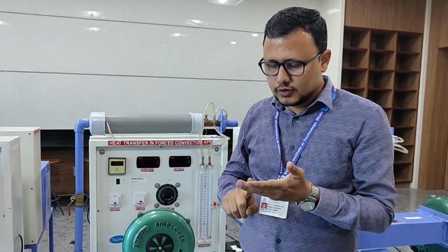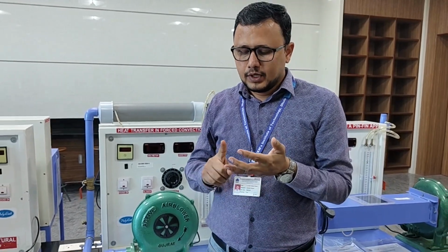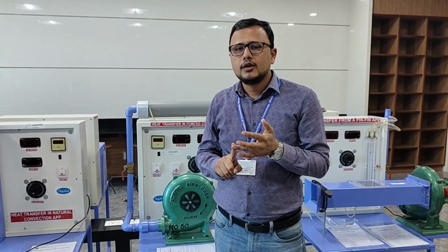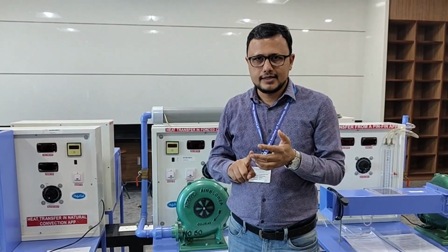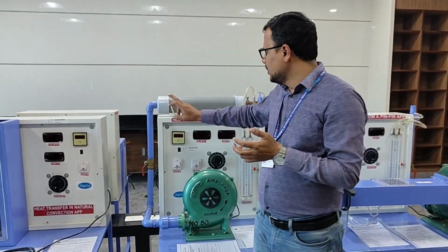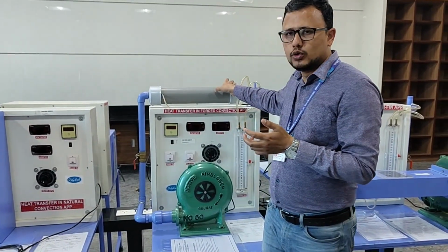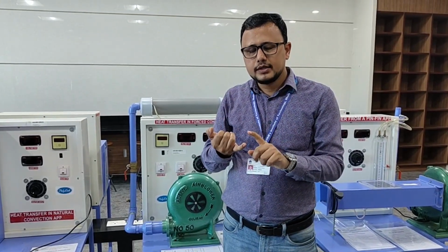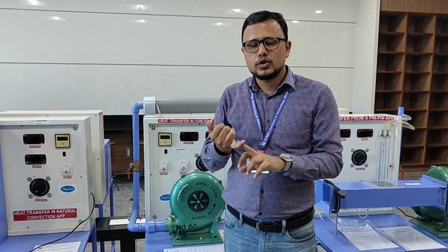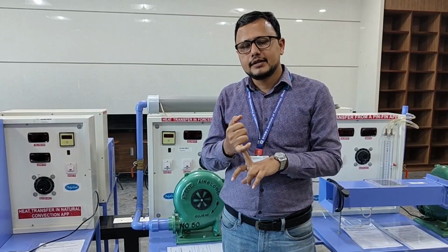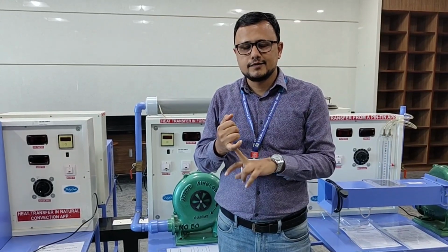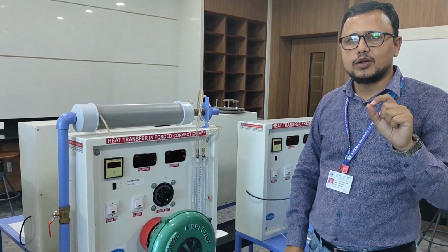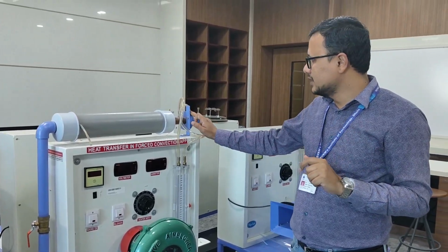And that's why, first of all, we will calculate mass of the air, then we will quantify the heat transfer to the air with the help of expression m Cp delta T. That delta T in that case will be temperature difference of air from the inlet to outlet. And once it is done, we will be able to compare the amount of heat which is supplied and amount of heat which is received by the air, and at that point we will be able to calculate heat transfer coefficient h.